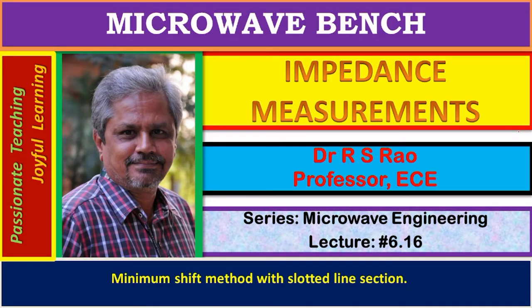Microwave bench impedance measurements, a series on microwave engineering, lecture number 6.16. Impedance is an important quantity in electrical engineering. It is complex and measured in ohms. Its real part represents resistance and the imaginary part represents reactance. Inverse of the impedance is admittance, measured in mhos or Siemens.